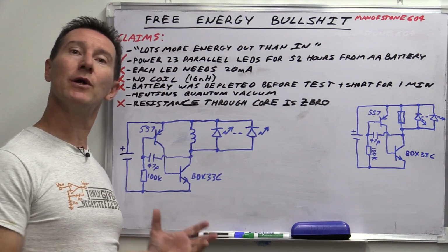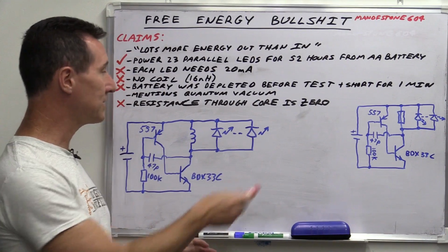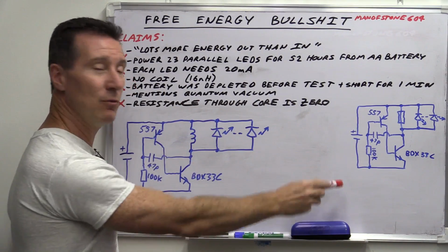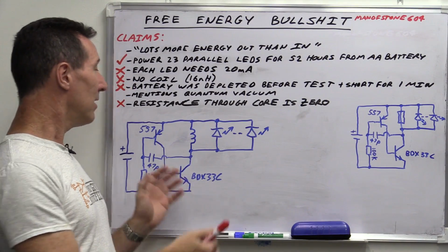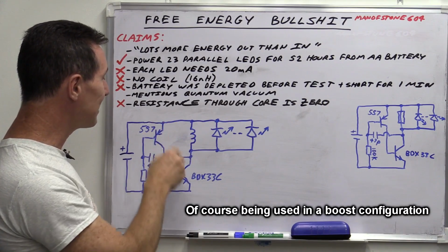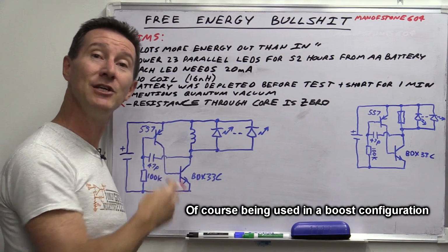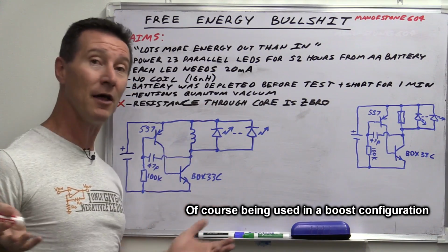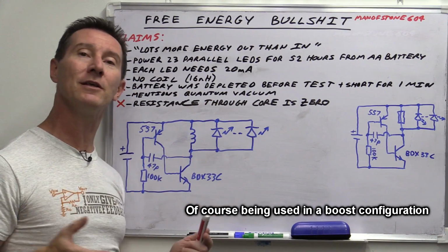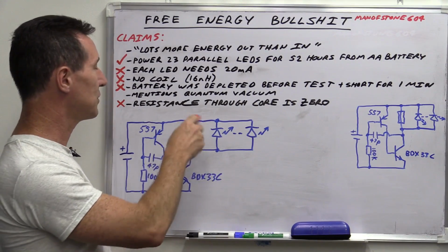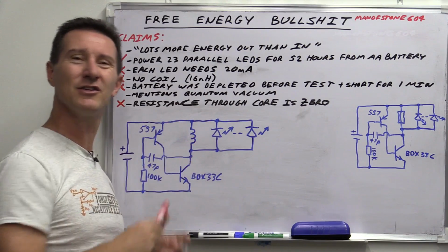So let's take a very quick look at how this circuit works. And yes, I've just redrawn it over here, a little bit bigger so we can draw stuff on it, and we'll draw some waveforms here. Now, clearly this is an oscillator. How do you know? Well, it's got this classic 2-transistor relaxation oscillator arrangement with the feedback capacitor in here. Nothing fancy at all. A lot of people think it's like a Joule Thief type variant. Well, a Joule Thief uses a transformer arrangement with a single transistor, kind of different.